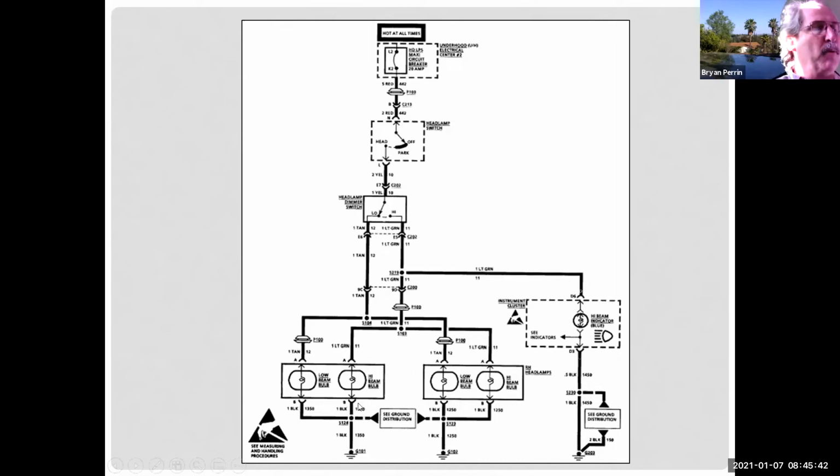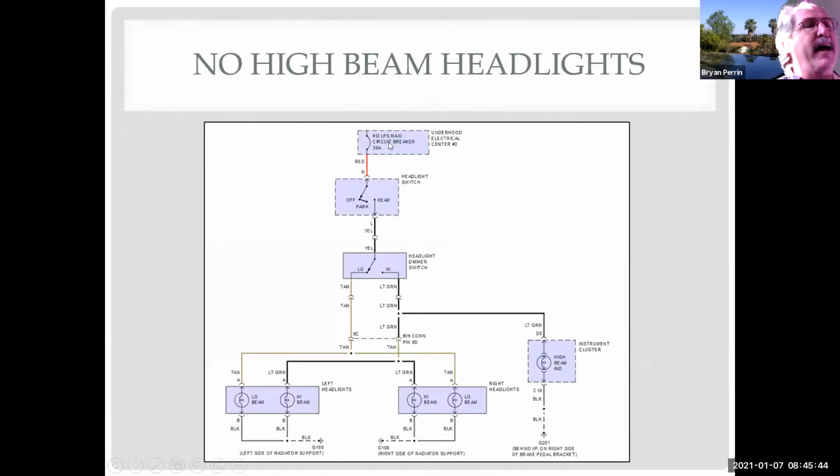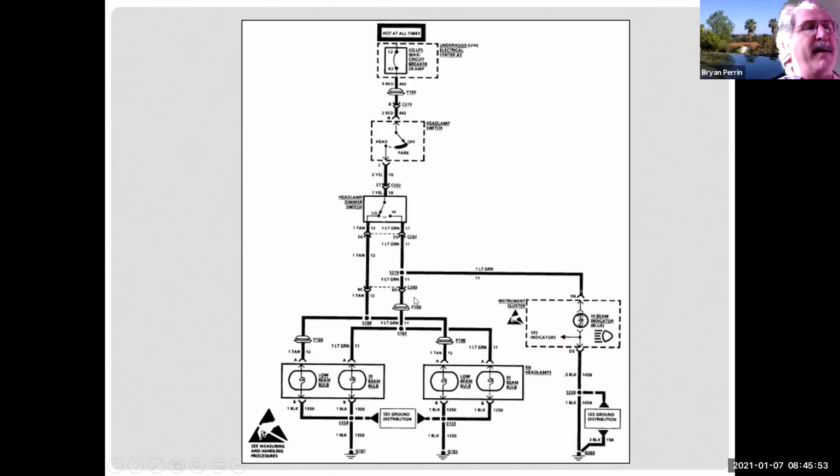So sometimes people will use the aftermarket schematic to do what we did and then go, okay, I need to know this number, or I need to know this number. Now I'm going to go into the factory schematic. I know what I'm looking for and get the number. So the reality is people tend to use both. I use almost all factory schematics because they have the detail level that I need to diagnose the car. But sometimes I'm not getting the relationship that I want, or I'm not getting the big picture.